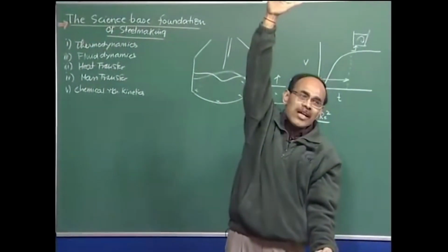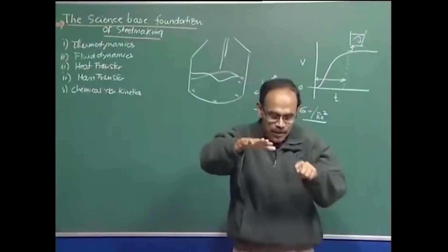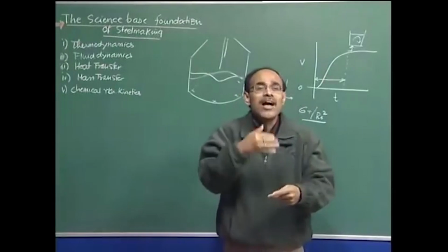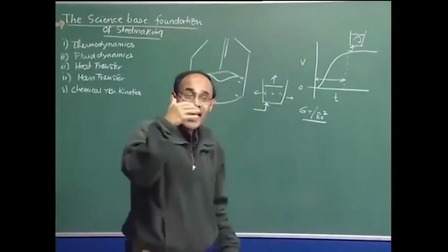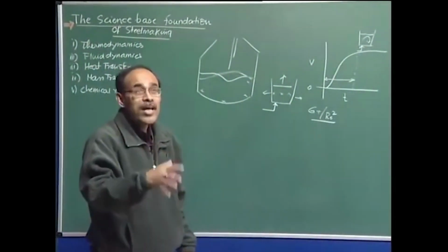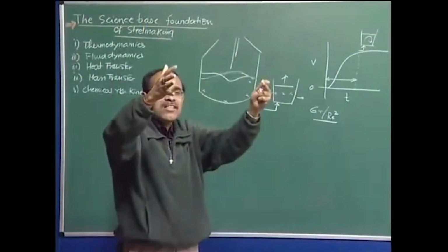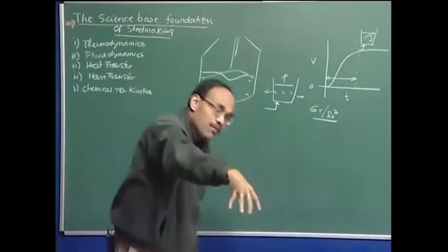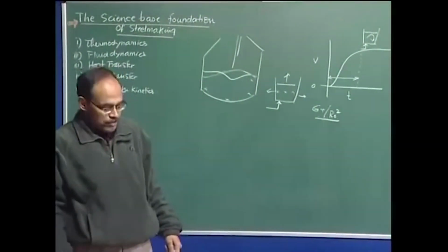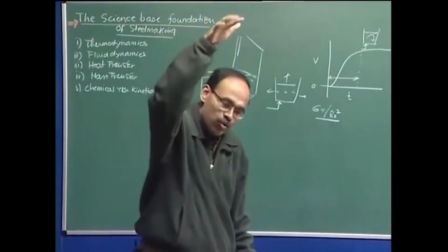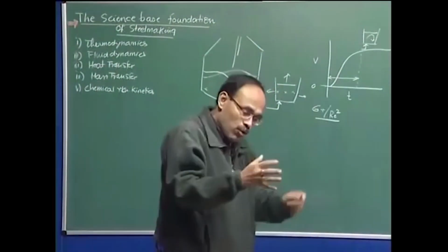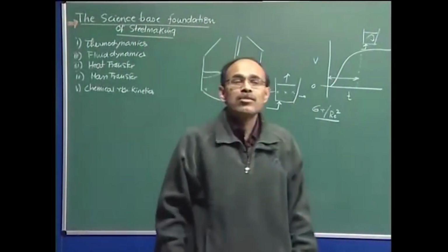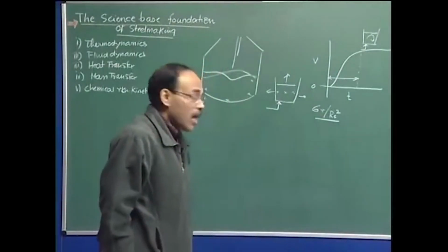Metallurgical length we are talking about is 10 meters or 8 meters. So I am talking about a distance of 7 meters down the meniscus where we may note some weak motion, and that weak motion, it is now well known, is a result of thermosolutal convection. Within the mold region in continuous casting, the flow is primarily driven by forced convection because of the impingement of the incoming jet of molten steel. On the other hand, towards the lower part of the strand where we still have some molten metal, any noticeable motion is going to be a result of thermosolutal buoyancy.